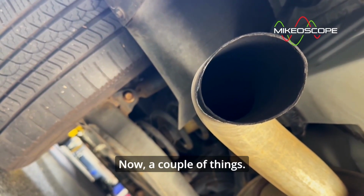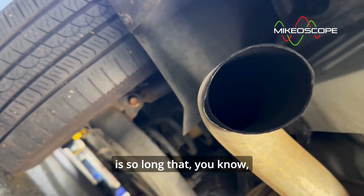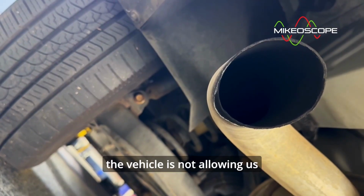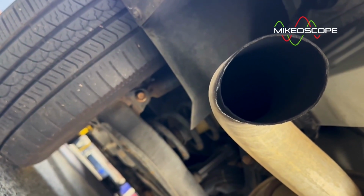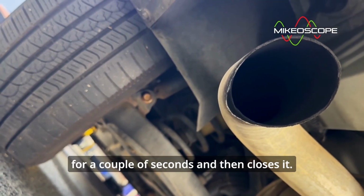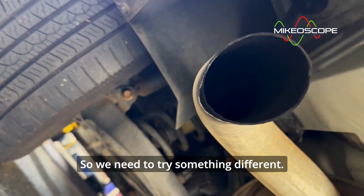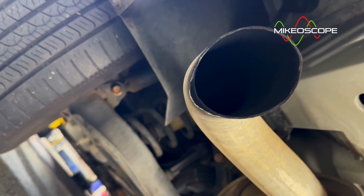Now, a couple of things. The reason why we don't see the smoke properly here is because the exhaust is so long that the vehicle is not allowing us to keep the valve open long enough to allow enough smoke to make it all the way here, because it just allows us to keep it open for a couple of seconds and then closes it. So we're not getting enough accumulation of smoke to come through here. So we need to try something different. This method isn't going to work.